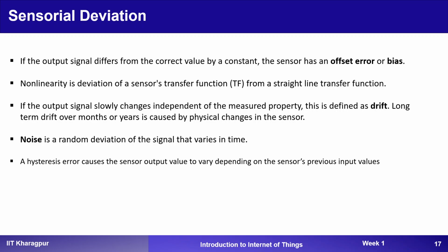It is not dependent on the value measured by your sensor; because of the fault, a value gets added to the measured value. For example, your sensor is always measuring 100 degrees Celsius. This is drift. It is not dependent on what your sensor is actually measuring, so it always gives a particular result.